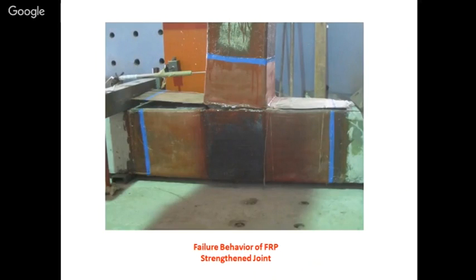After testing, how will the FRP fail? I told you FRP is flexible, but after epoxy, it becomes rigid. So you can see this image after testing under cyclic load to simulate earthquake performance. The FRP completely came out. The FRP which was affixed on the column portion completely comes out. The reason is improper or inadequate anchorage. Your epoxy will perform up to a certain limit, and not more than that. So if you want to increase the performance, we have to improve the performance of the epoxy. The bond strength between epoxy and FRP is very important. Otherwise, this kind of bonding failure will occur.